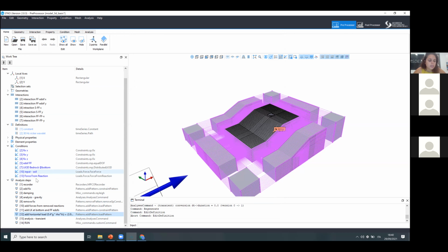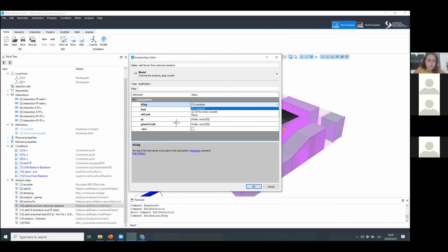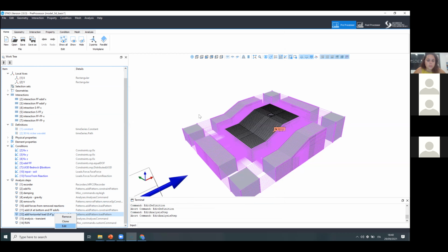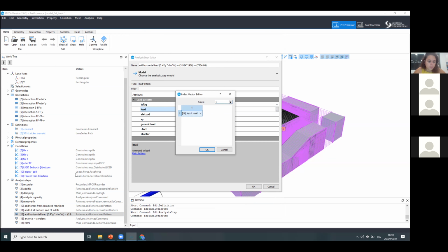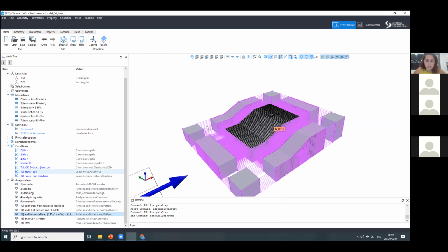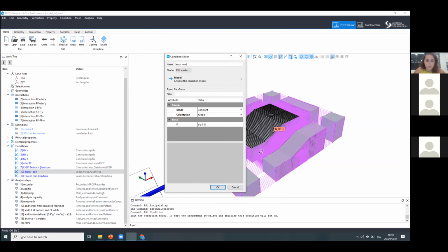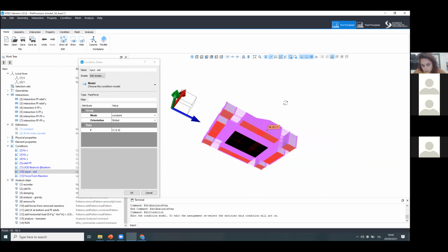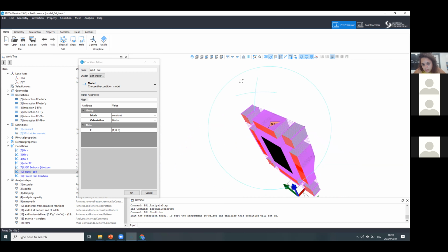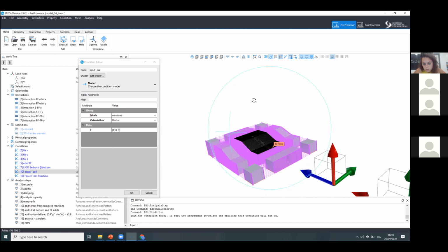He created a load pattern in which it references just the constant one, and then another load pattern in which it references this wave with a specific factor, and inputs here a force called input soil. And this input soil is actually a unitary force applied to the base of this solid structure.